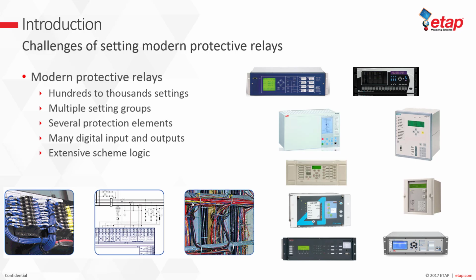Relays communicate and are interlocked with other protective devices to exchange protection and control information to enhance and accelerate protection and control system performance. Relays also have become very flexible while requiring extensive customized scheme logic to be set by the user to be fully operational in practice.